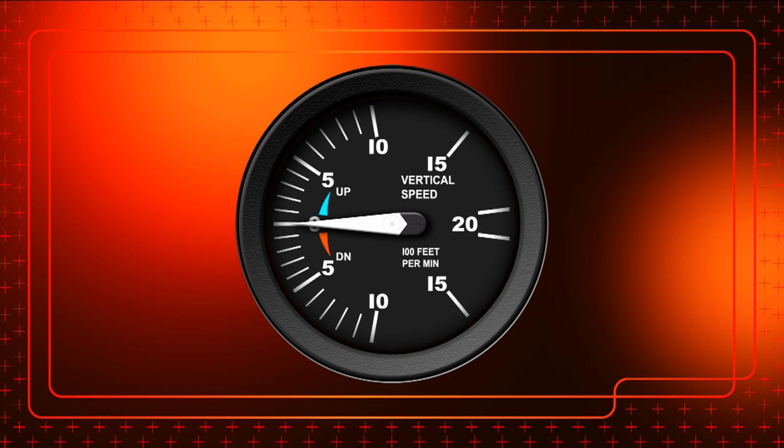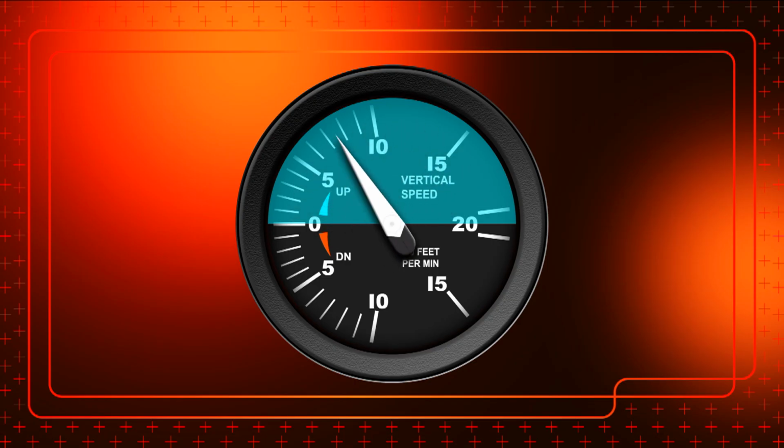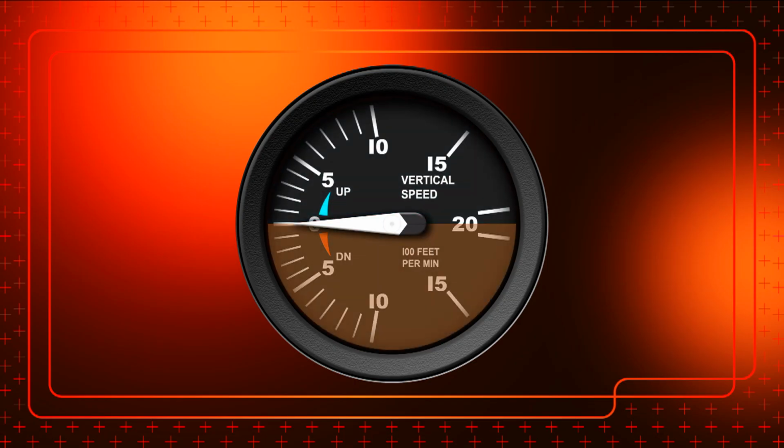In order to quickly tell which is happening to the aircraft, imagine that the instrument is split in half horizontally, so all the scales in the top portion of the instrument, which we have highlighted in blue, represent a rate of climb, and all the scales in the bottom half portion of the instrument, which we have highlighted in brown, represent a rate of descent. You will also notice that the instrument actually states this by means of having up written by the blue arrow pointing in an upward direction and down written by the brown arrow, which is pointing in a downward direction. So the instrument is quite intuitive in this way.